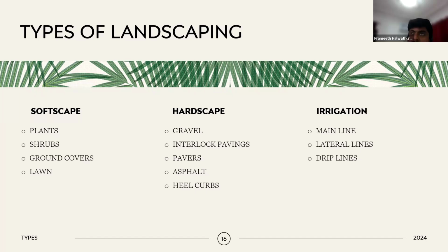Normally for the trees, we use as per the site, normally around the circumference of the tree area, 6 meter, 4 meter, 3 meter, as per the sizes of the trees, the conditions, and the specifications. Drip tubes are for the plants, shrubs, ground covers, which want water.